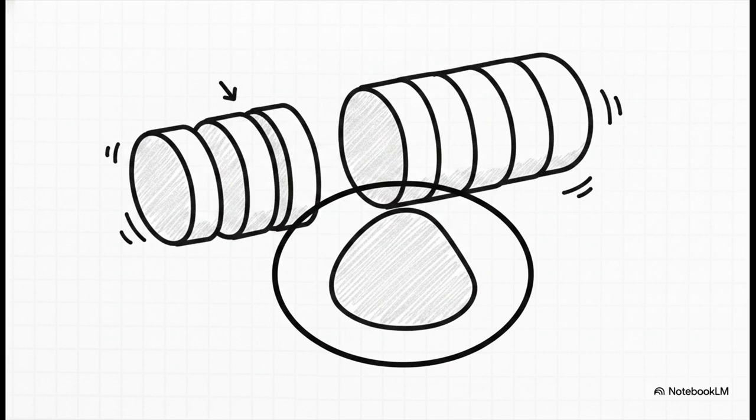The standard dictates that this applies independently at any plane. That means each individual slice can actually have a slightly different center point, as long as the surface of that specific slice is perfectly sandwiched between its own two concentric circles. So it definitely catches if a slice is oval-shaped or egg-shaped, but it doesn't care at all how those slices stack up against each other.